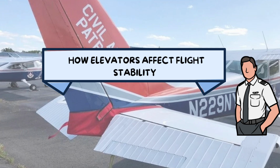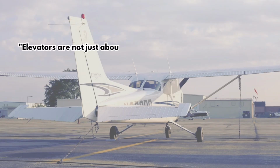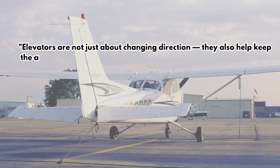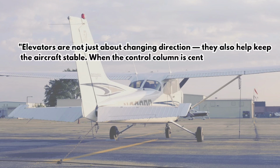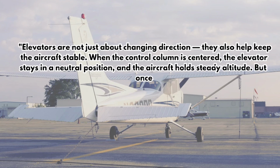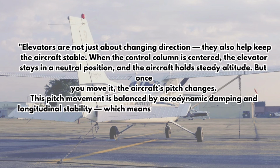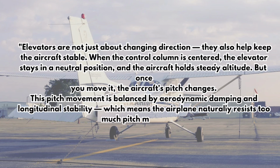How elevators affect flight stability. Elevators are not just about changing direction, they also help keep the aircraft stable. When the control column is centered, the elevator stays in a neutral position, and the aircraft holds steady altitude. But once you move it, the aircraft's pitch changes. This pitch movement is balanced by aerodynamic damping and longitudinal stability, which means the airplane naturally resists too much pitch movement.